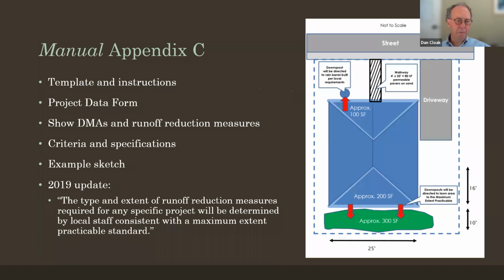However, at the same time, I can say that in my own experience, I have seen more cases than not where the expertise of the geotech was, yes, it's completely acceptable to put in an impermeable vertical liner, typically plastic, on the side of the bioretention facility or dispersal area to protect the foundation. And so as long as that's there, they're comfortable with it.